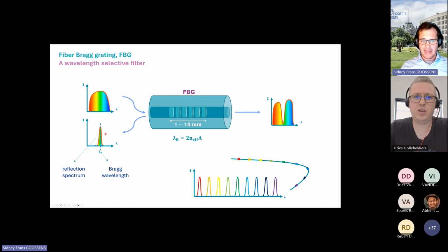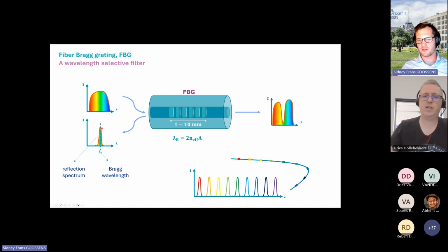So it actually depends on how accurate your measurement system is and which increments of wavelength change you can measure with it. There are very high resolution systems that can go up to sub-degree. Typically, the resolution that you can measure is 1 picometer, which is a tenth of a degree, I think. But you can go with higher resolutions, you can go lower than that. Usually they mention on the spec sheet half a degree as the accuracy. But a tenth of a degree is certainly possible. And like I said, by increasing the sensitivity of the measurement device, you could go even further than that.